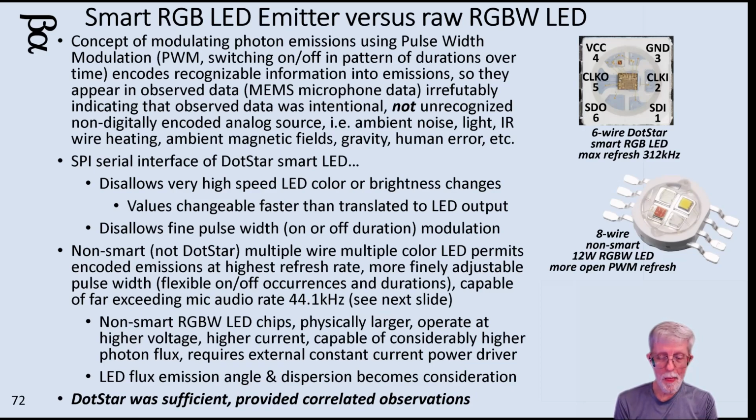Now, if you're curious, the chip in the upper right-hand corner is all 4 of those chips, but the yellow-looking little square inside the device is the white one, because the chip is actually producing a particular wavelength of ultraviolet, and then it's got a phosphorescing material layer on top of it, and that causes it to produce a broad spectrum of white. That's how white light bulbs work in your house nowadays: the individual chips are deeply ultraviolet, and then the plastic covering on the outside of the bulb has a fluorescent material that makes it white.